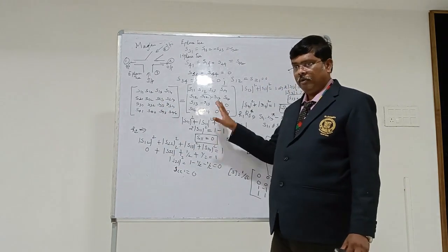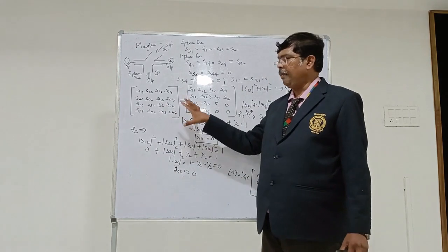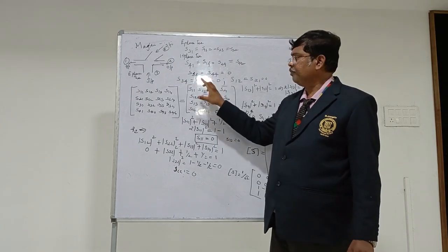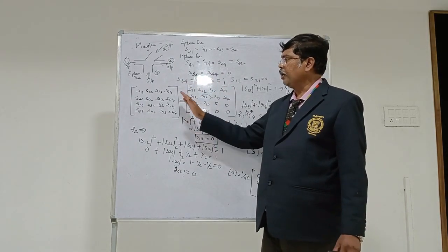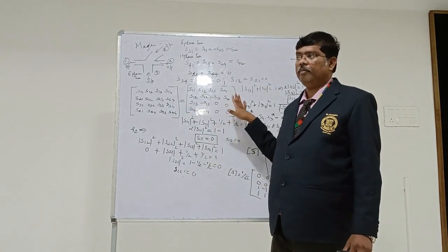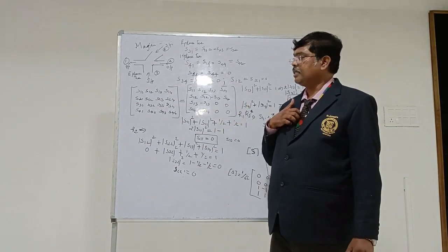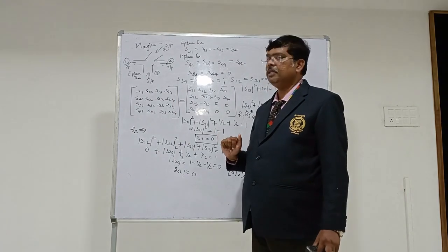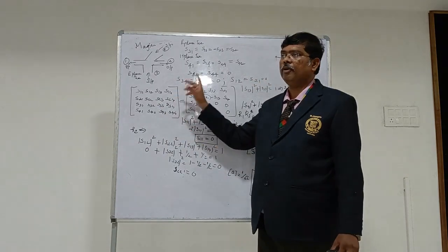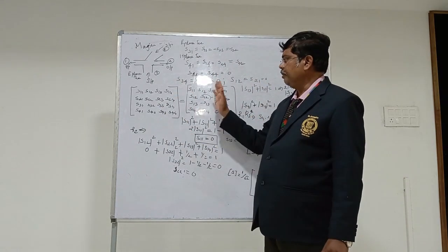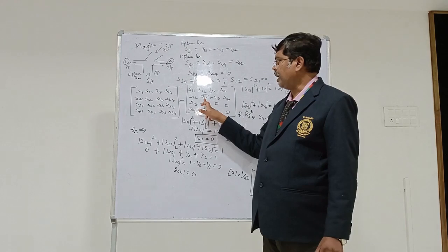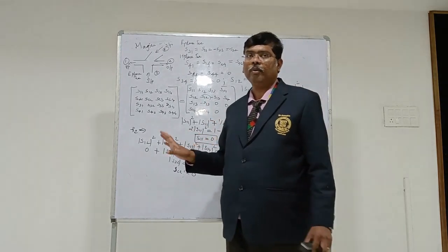This is the way I did it in the E plane T and H plane T, the same way. I am writing the general 4x4 matrix because this is a 4-port network. The first row stays exactly as the first row, and I replace rows 2, 3 and 4. For easier calculation, instead of calculating all 12 elements, I replace the row 2, row 3 and row 4 elements with the help of row 1 elements. Using the symmetry property, most of the elements can be replaced using row 1 except S22, because the i and j values are the same, so this condition will not work here.